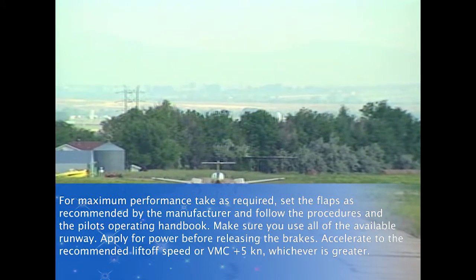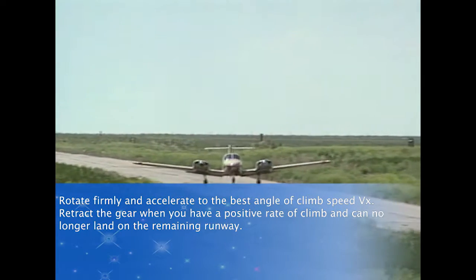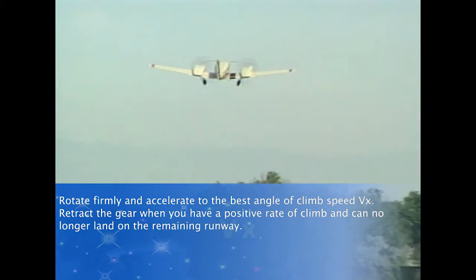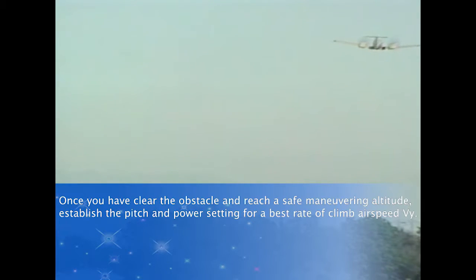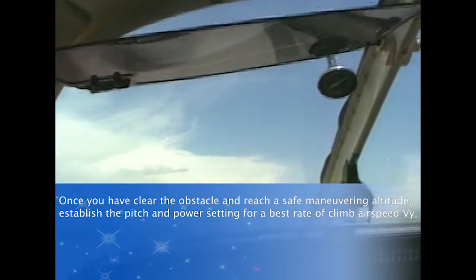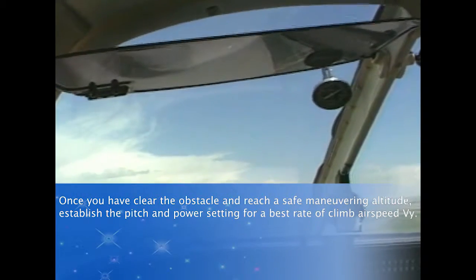Accelerate to the recommended liftoff speed, or VMC, plus 5 knots, whichever is greater. Rotate firmly and accelerate to the best angle of climb speed, VX. Retract the gear when you have a positive rate of climb and can no longer land on the remaining runway. Once you have cleared the obstacle and reached a safe maneuvering altitude, establish the pitch and power setting for best rate of climb airspeed, VY.